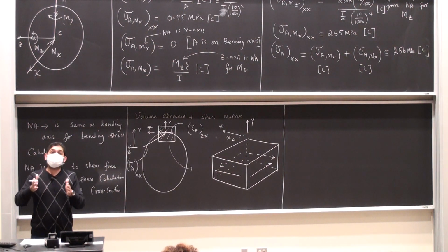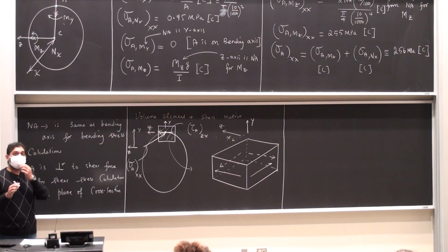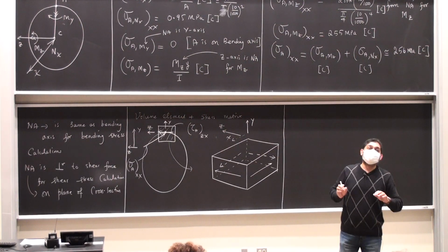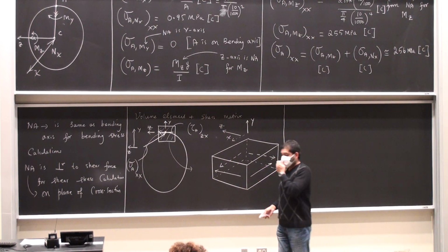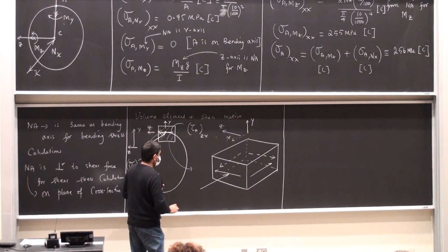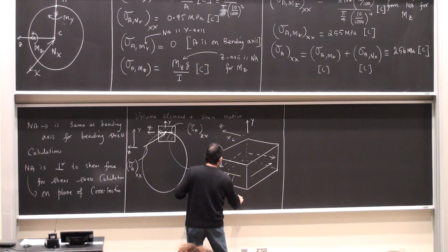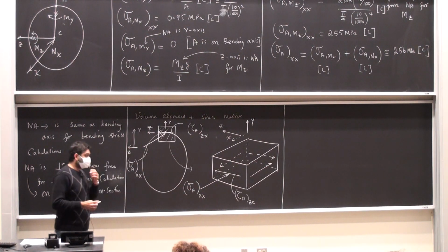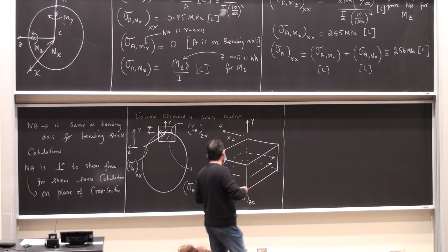This is the effect of the shear stress, but on the same volume element, because you have a combined state of loading, there is also going to be impressing upon itself the normal stress sigma AXX. So on the face that you see, I'm going to have a normal stress pushing into the face. This is sigma AXX. This was, of course, tau AZX, and so on. Which means on the opposite face, I need to have something equal and opposite to sigma AXX.